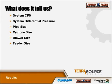If the system's designed too small, obviously, it won't convey the material properly or at all. You have material just sort of slugging down the pipe as pressure builds up behind it, then shoots forward a little bit more, and pressure builds up, and it's not efficient at all, with increased wear. And then a system designed too large is also a problem, because you don't want to waste power, and you could have too high a velocity and the air just runs over the material. So in either case, it's very important to define a set of specifications and stick to them.